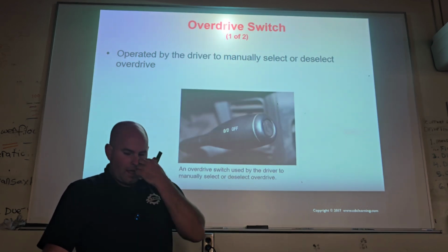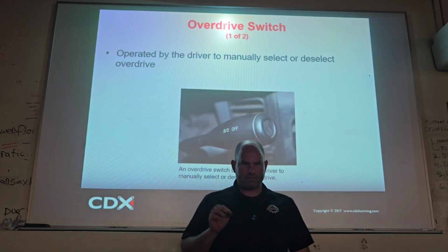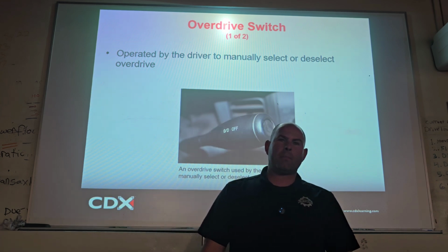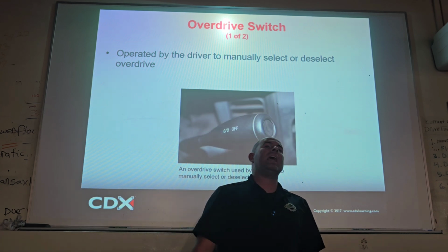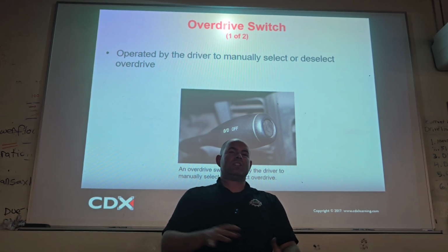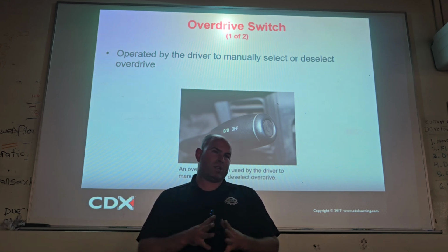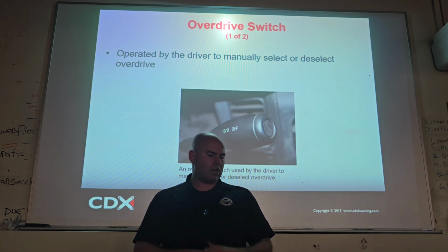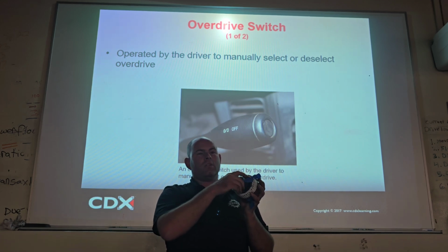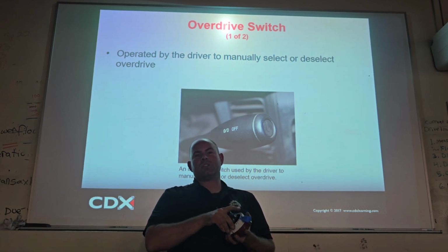Cool. And then overdrive switch. Who is not totally sure what overdrive means? It's okay, because I've heard quite a few different songs talking about put it in overdrive. I heard one, put the engine in overdrive. The engine doesn't go in overdrive. And additionally, if you did put the transmission in overdrive, that wouldn't be for more power. Remember when we talked about the planetary gear set? Underdrive gives you more torque. What's overdrive give you? More speed with less torque. So now do you understand what overdrive is?